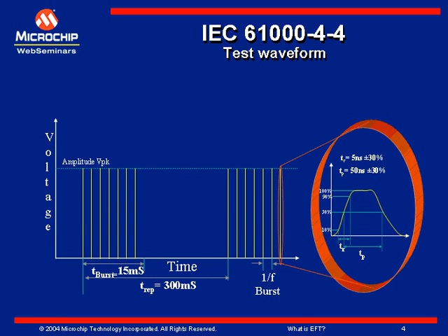As per the spec, there will be 15 milliseconds of on time where you will have multiple pulses, and then the whole signal repeats after 300 milliseconds. So actually you have 285 milliseconds of off time. The figure is not to scale. It doesn't seem that you have enough off time, but actually the off time is much bigger than the on time.